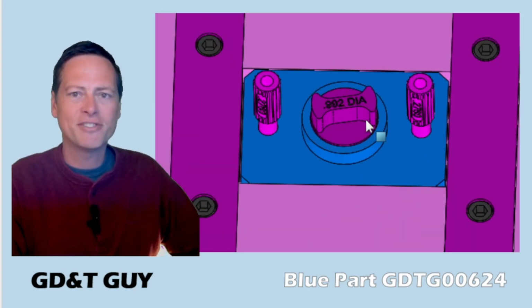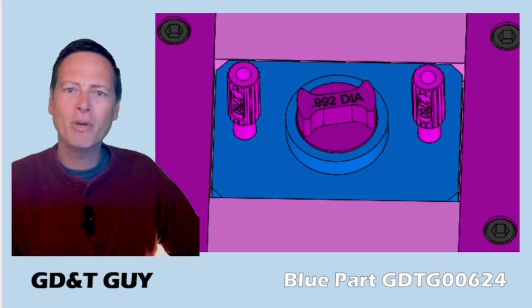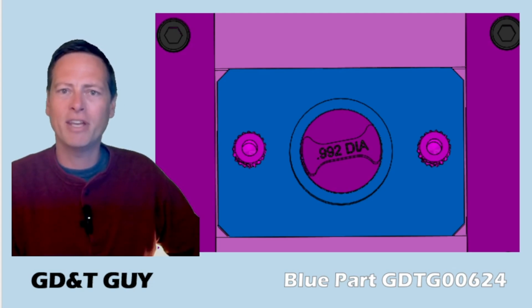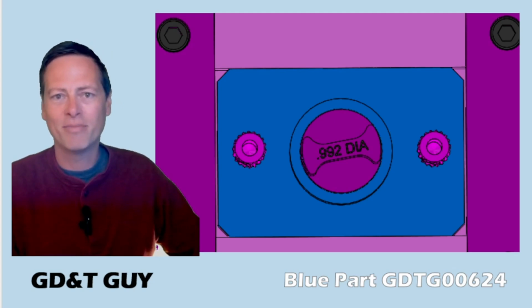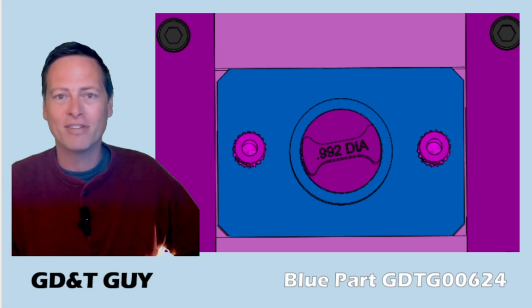One thing that is interesting is that because the size tolerance for the datum B feature is so much tighter than the size tolerance for the datum C feature, it kind of helps justify datum B as being a secondary datum and datum C as being a tertiary datum. But kind of on a similar line to what I was saying before, it is also easy to imagine the 3-inch wide datum C feature being made near its MMC, right?